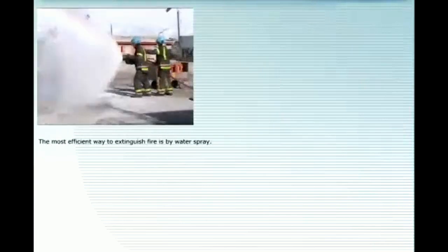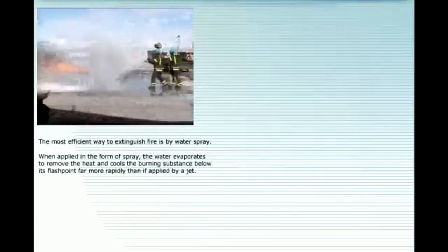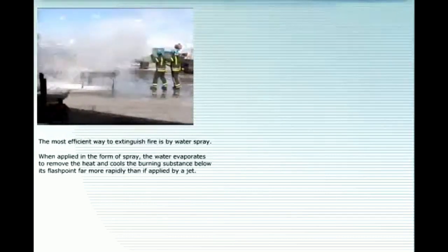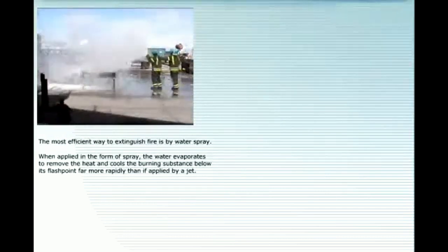Normally, you should combat fire by spray. When applied in the form of spray, the water evaporates to remove the heat and cools the burning substance below its flash point far more rapidly than if applied by a jet.